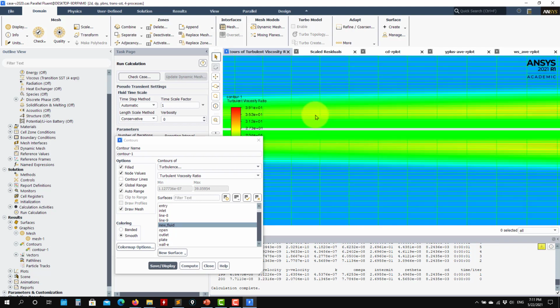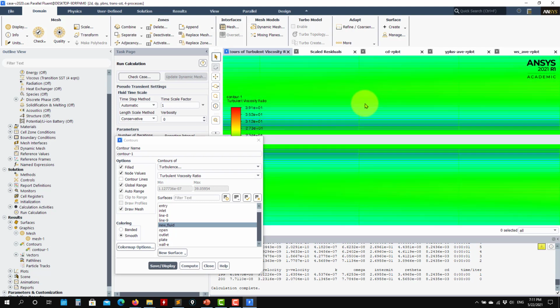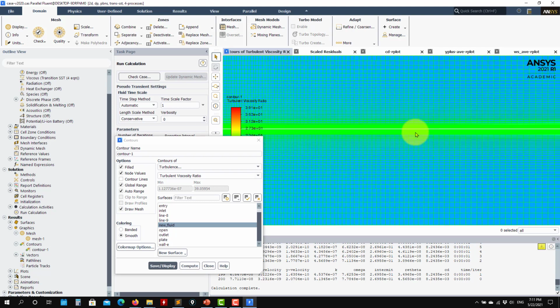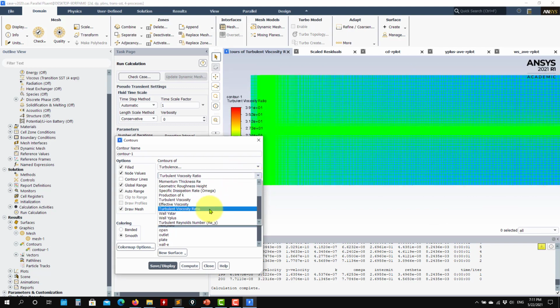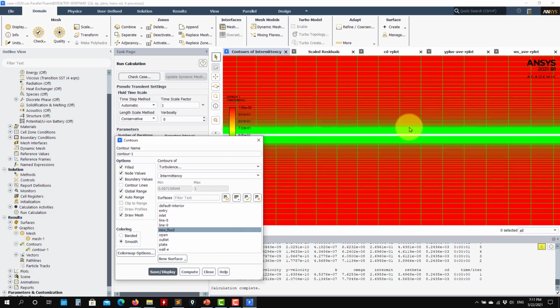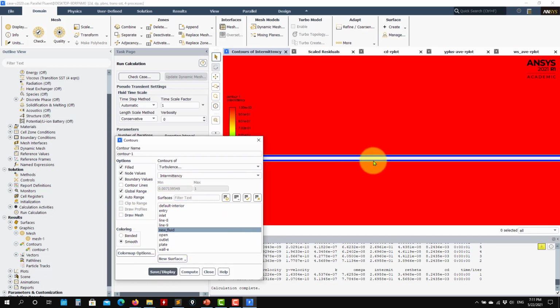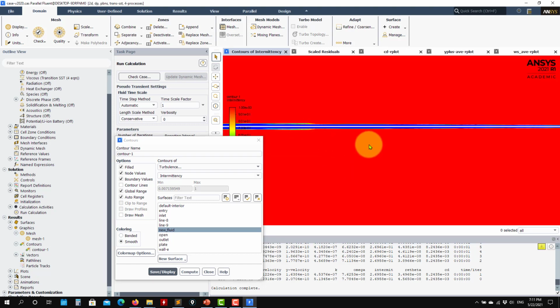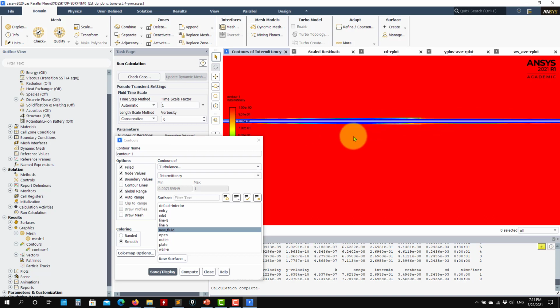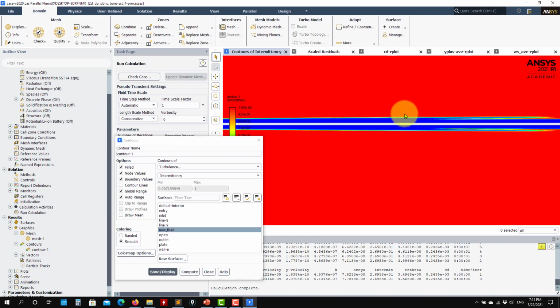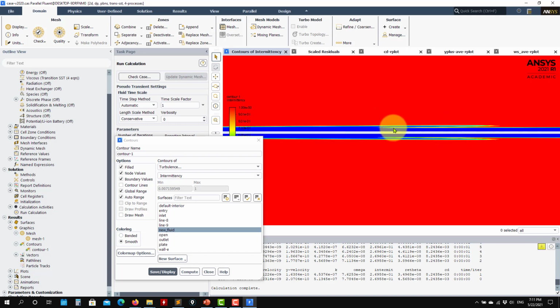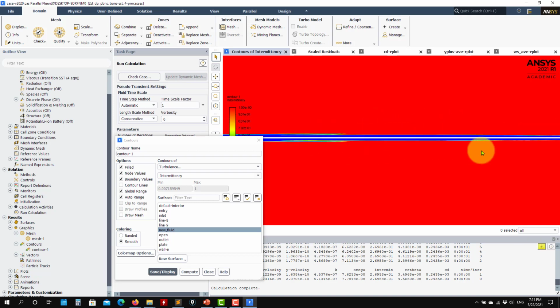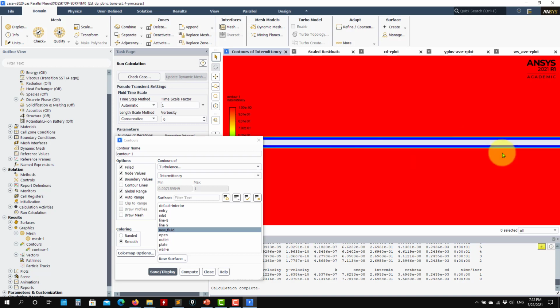This mesh is resolving, even as you go here, see that you're clustering enough cells to resolve the velocity gradient normal to the wall. And the other quantity to look at, besides your traditional quantities, is intermittency. This one is telling you, let me now switch off the mesh, where you have laminar or turbulent flow. See that all this region is laminar, okay? It's a sizable region normal to the wall. Then usually you see this behavior means the transition already here, and see that it is now transitioning to fully turbulent. The laminar region is becoming thinner, and so on.